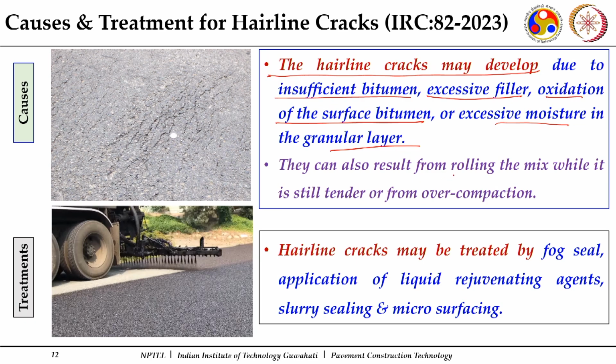This may also happen if the mixes are rolled when the mix is still tender, that is, quite soft. As we discussed earlier, a good amount of initial compaction is done by the pavers, which give some vibrations to your loose mix.